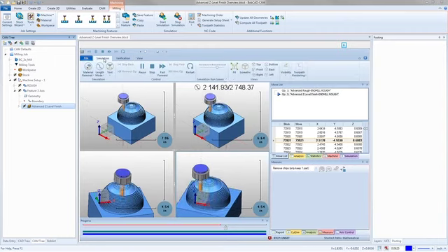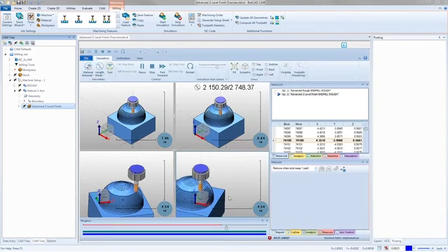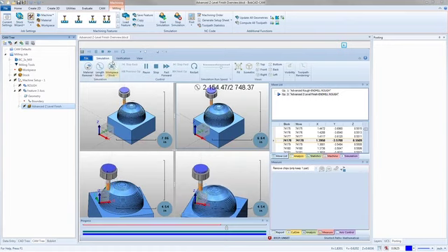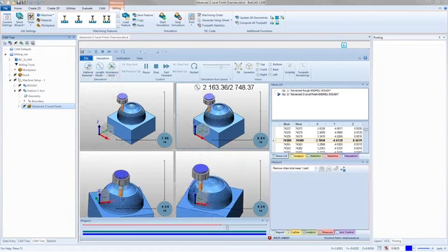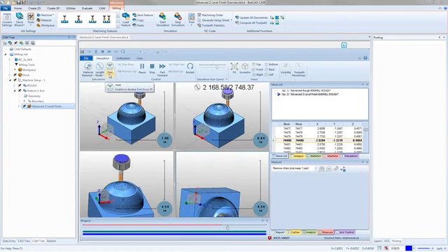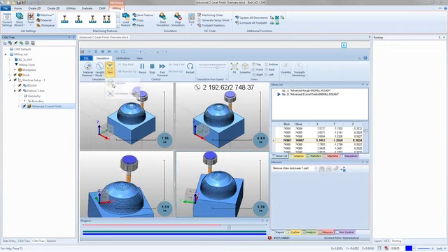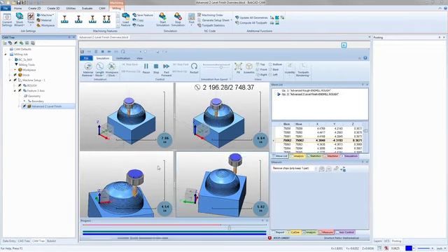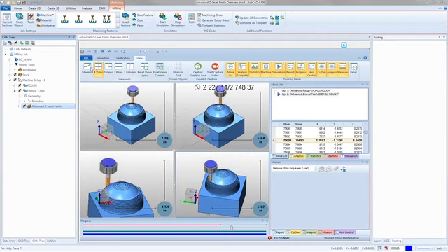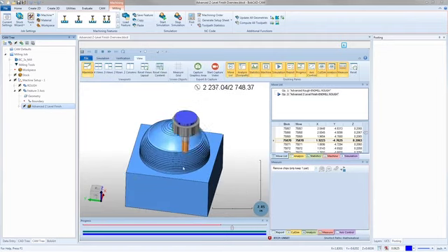So you can go in and actually check the simulation, and you'll see right here, when I click on this, the workpiece stock option is set. But if I click on this one, the tool is set. So I rotated it too. Let me zoom out there. Whoops, fit. There we go. So if I want to change that, all I do is go tool, workpiece stock. That's going to lock it in. And now they're all locked. So each individual window can have different settings. When you want to bring it back to one, we can go back up to view and just say maximize. And there we go right there.